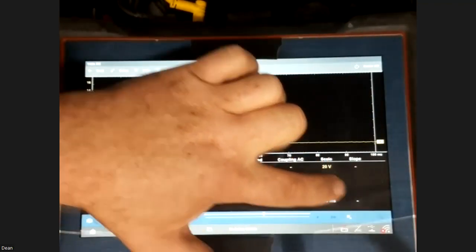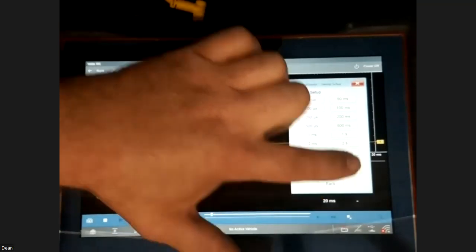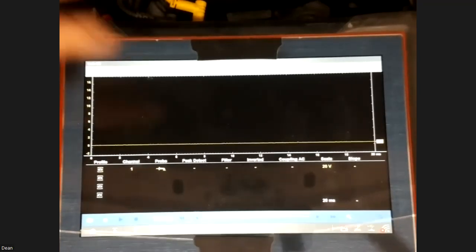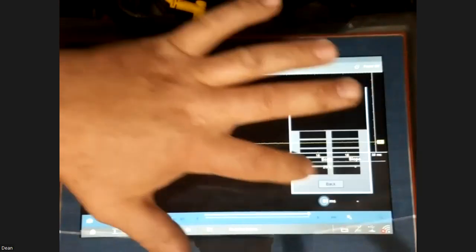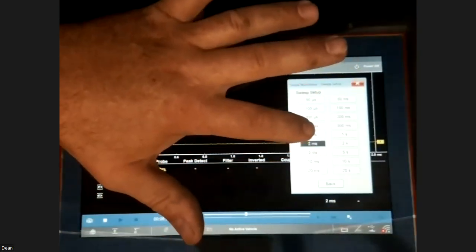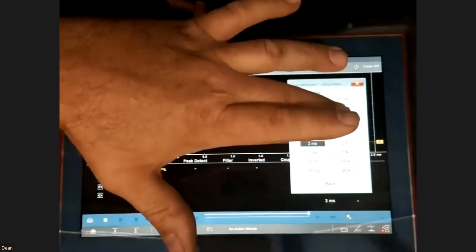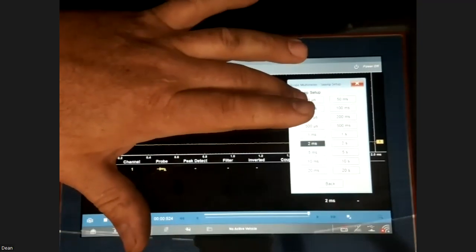max. And the best thing that I can give you right now is set up your scope for 20, 20. 20 volts, 20 milliseconds, go from there, start sampling, start doing different things. If you can't see the signal correctly, go to 2 milliseconds. I'm not going to get into that. That's a whole couple hour training module of getting into milliseconds, seconds, and nanoseconds.